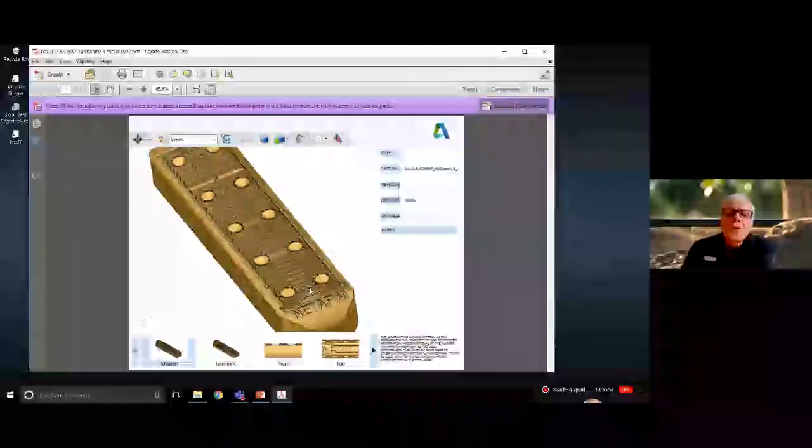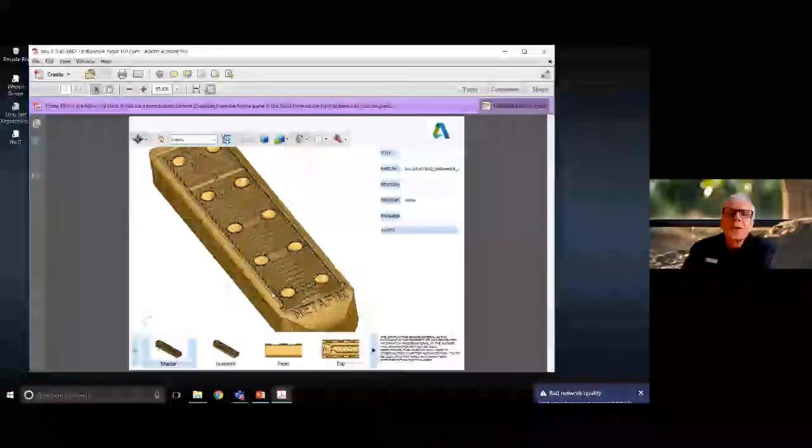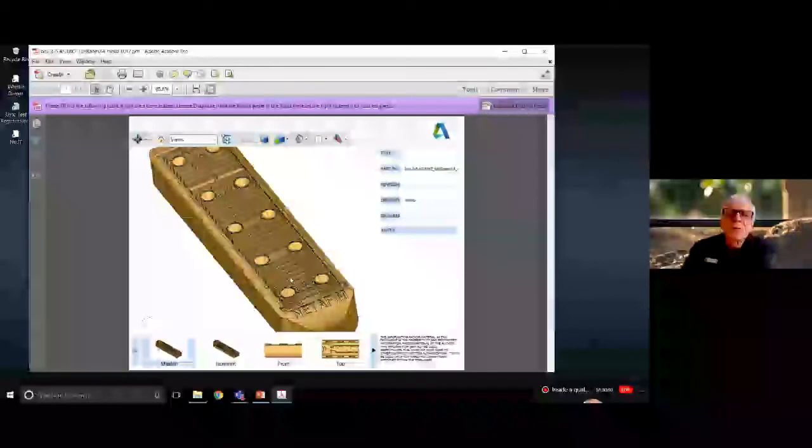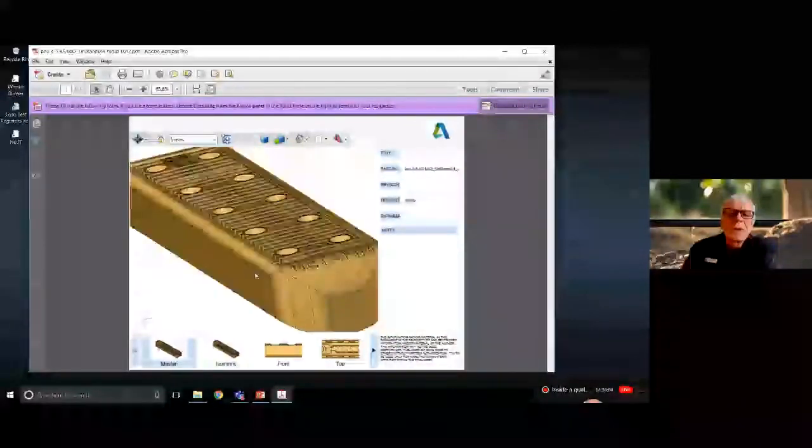Then, if we now have a look, you've got the water entering this vein, and this vein slopes away and goes towards this channel going down the side of the dripper. So we've got all the water entering this vein, and then this vein, and this vein, and so on and so on. So the flow rate entering this channel has to get larger. So we've got to make this channel bigger, but this distance from here to here cannot get bigger. So what we've done,